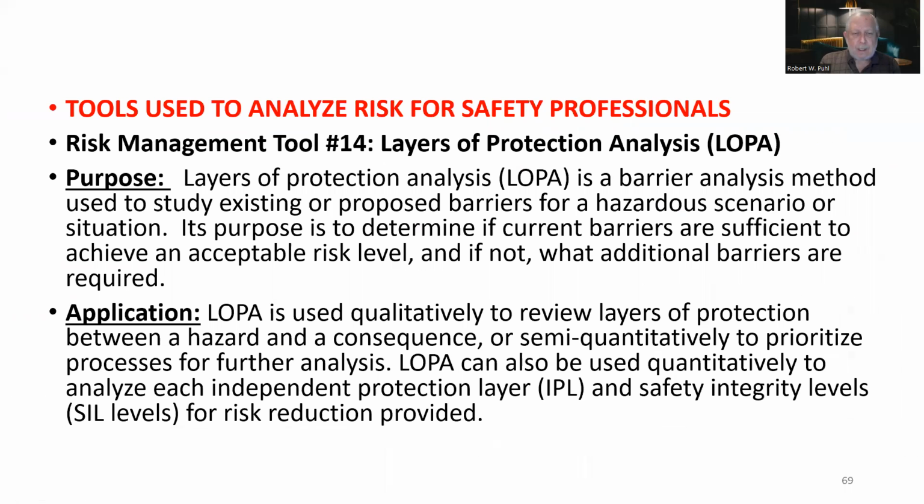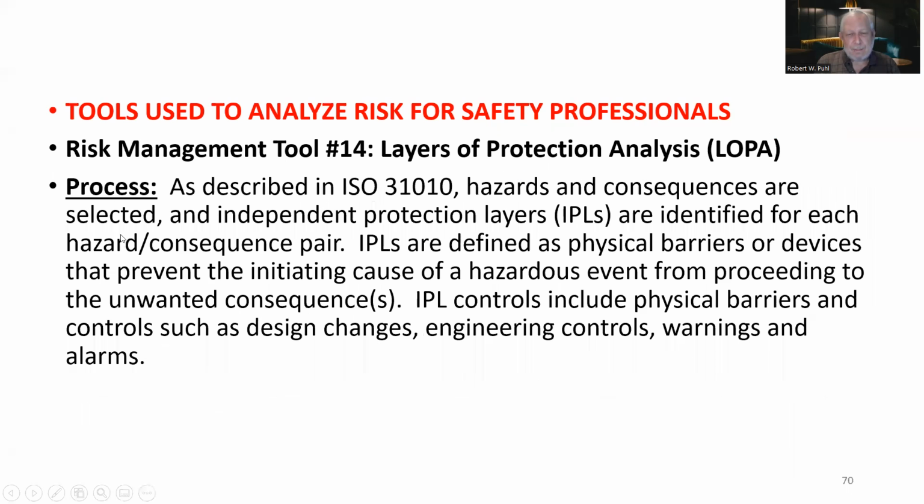Application: LOPA is used qualitatively to review layers of protection between a hazard and a consequence, or semi-quantitatively to prioritize processes for further analysis. LOPA can also be used quantitatively to analyze each independent protection layer, IPL, and safety integrity levels, SIL levels, for risk reduction provided.